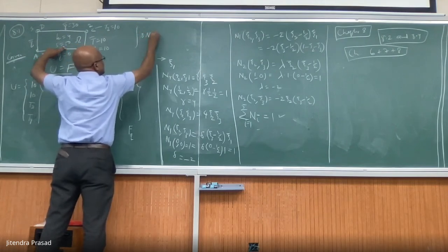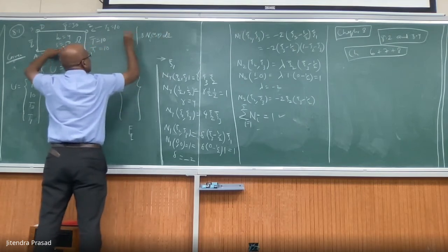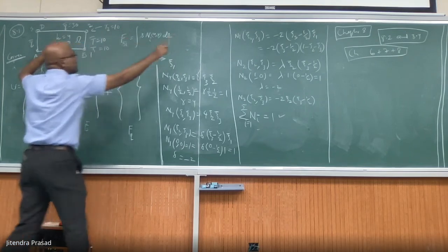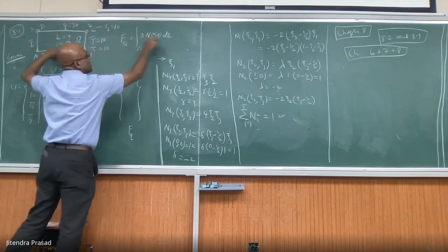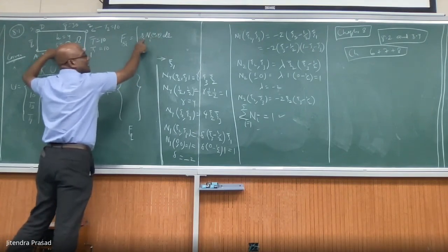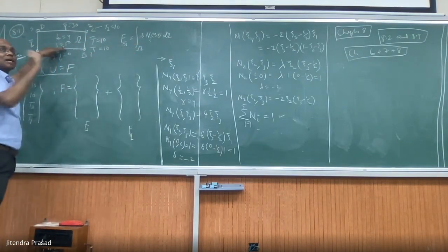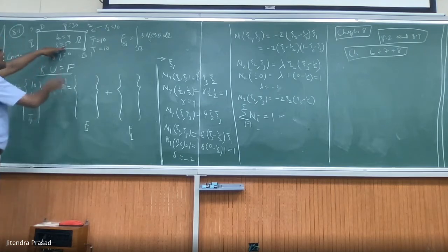Either you can write this as F_i equal to the integral of the source value multiplied by the shape function N_i over the whole domain. Remember, in 1D you also had something like this: you have the source value multiplied by the shape function itself, and then you integrate over the whole term and you get it.